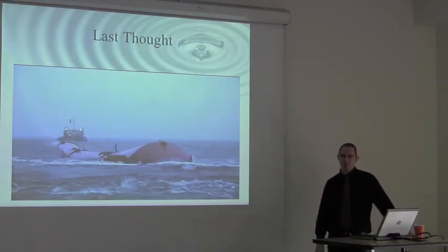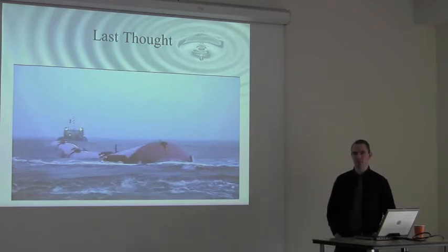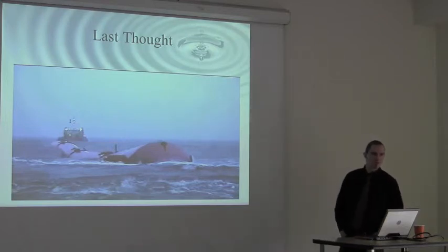Yeah, and also, Dr. Brecken, there's some work done at the University of Rhode Island by Stephen Grilly, where you have a heaving cylinder that is dominated by the first harmonic, like you're saying, but he attached several different cylinders of different lengths and different diameters all into one device, and increased the broadband response of the buoy. So when you put it into a real sea, where you have changing wave conditions, then the broadband response is more important.